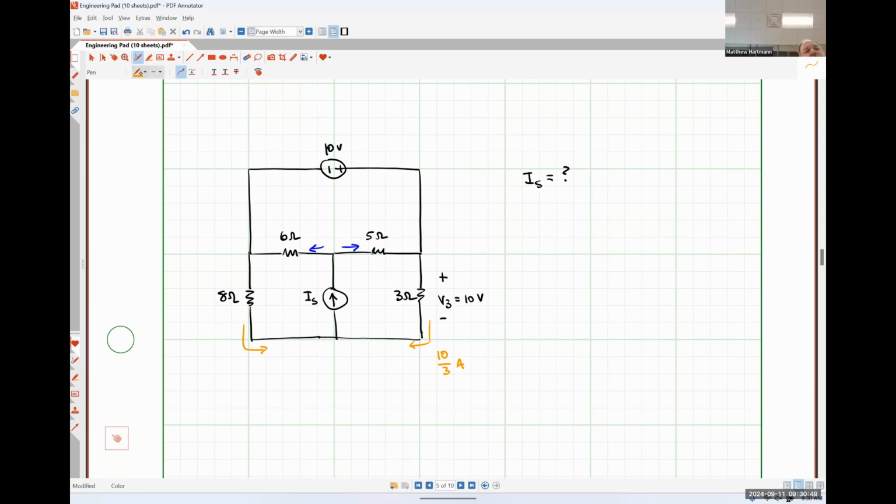So how might we find the voltage drop across the 8 ohm resistor? And let's just arbitrarily define that voltage as positive polarity on top, like so. When I'm trying to find voltage, I'm probably thinking about Kirchhoff's voltage law based on the amount of information that we currently know in circuit analysis. So is there a way that I can apply Kirchhoff's voltage law to this system to find V8 based on the information that I already have? Do the law around the outside, absolutely.